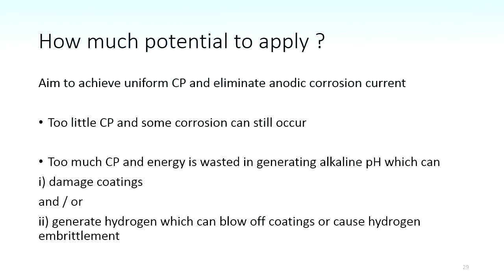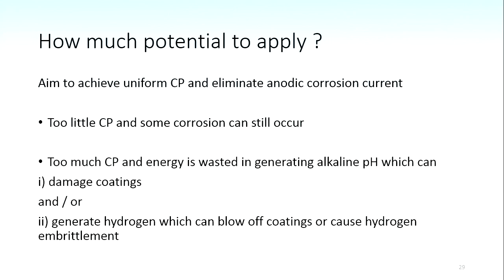If you apply too much, then apart from wasting energy, you're also changing the local pH. It becomes alkaline around the cathode. That can have a negative effect on the coating. Okay, they don't like alkaline pHs particularly.